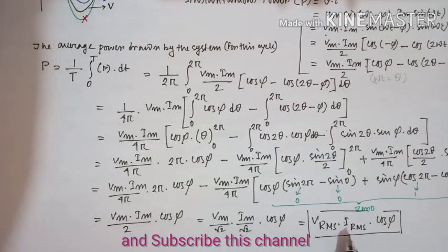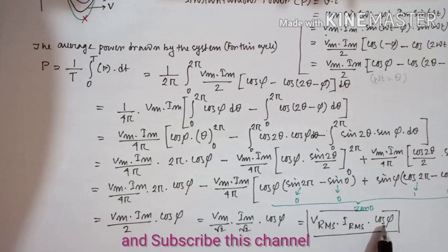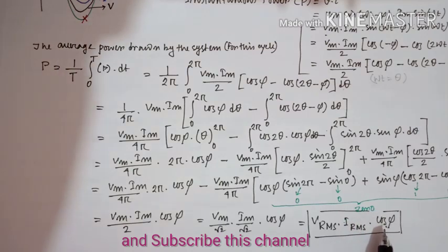So the multiplication of the RMS values multiplied by cos phi gives us the power in an AC system, where phi represents the phase difference between voltage and current, and cos phi is called power factor.